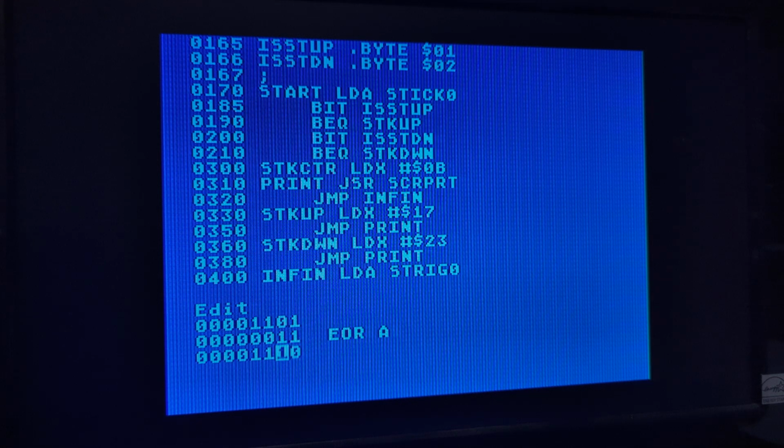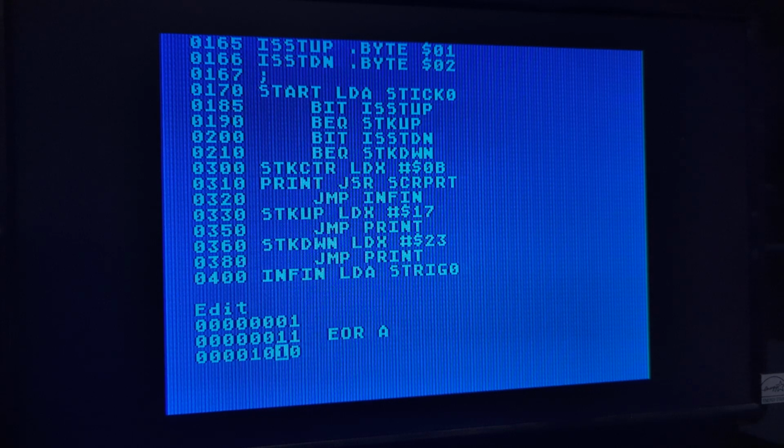So with the exclusive OR, for every bit I set, it toggles the original bit to its opposite. When I have a 0, it changed it to a 1, and when I have a 1, it changes it to a 0. So what you use exclusive OR for is to toggle certain bits.